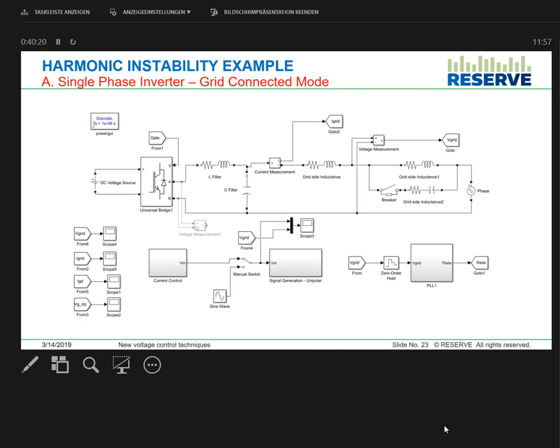So this is the single phase inverter with 4 switches, and you have the LCL filter, which is the output filter of the converter, and this part is something that is unknown. It belongs to the grid impedance. I just connected to the socket which I call the grid, and then whatever impedance is there after that, I really don't know.